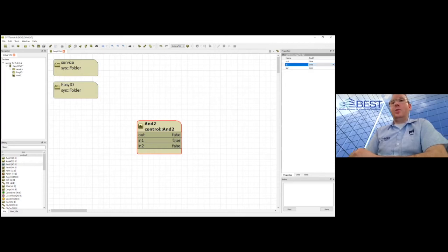Okay. Do not use null values here. Null values are a way of saying, I don't know. And it will result typically in the control block saying, well, if you don't know, I don't know. And unfortunately, I don't know has a tendency to break programs.